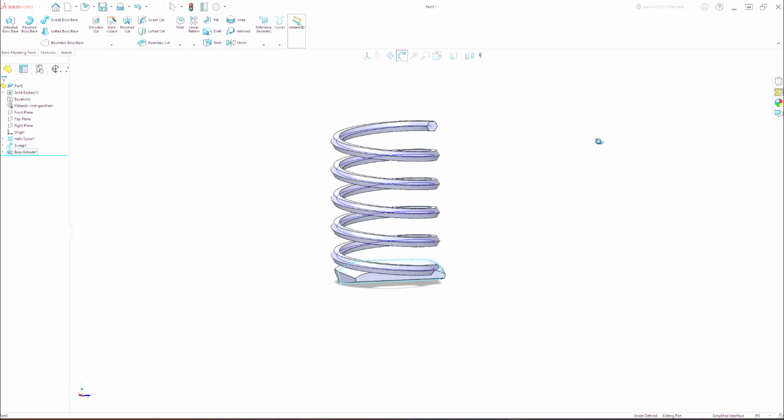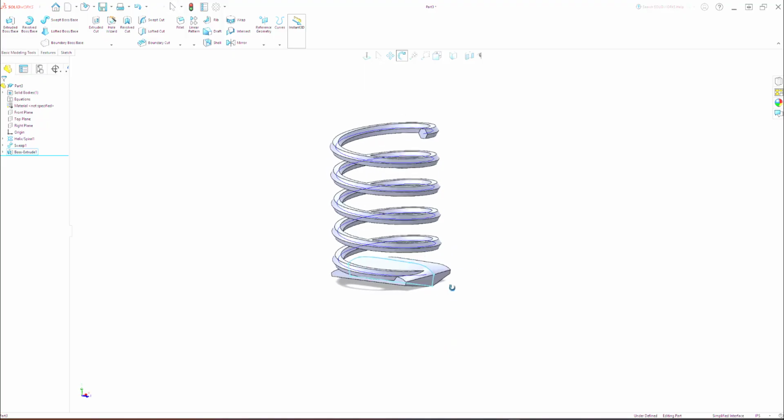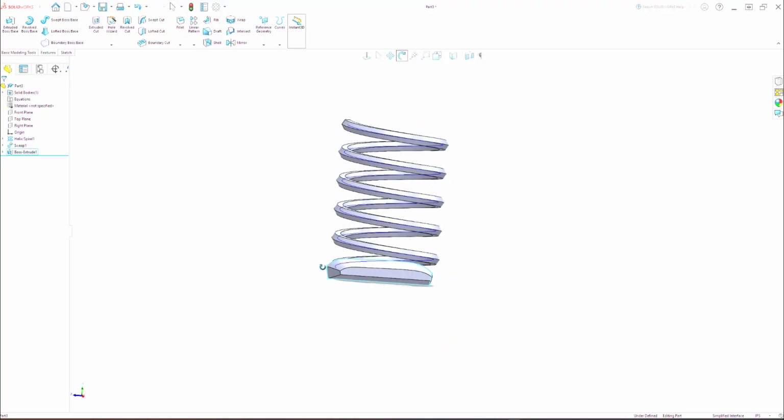But again, the next step would be to create a sketch on the top, create a simple or another component to be able to compress with. And if you do want to create a post to maintain the rigidity of vertical movement as opposed to horizontal movement, you could create a post and a hole in the top object. So this object only slides vertically along the object.